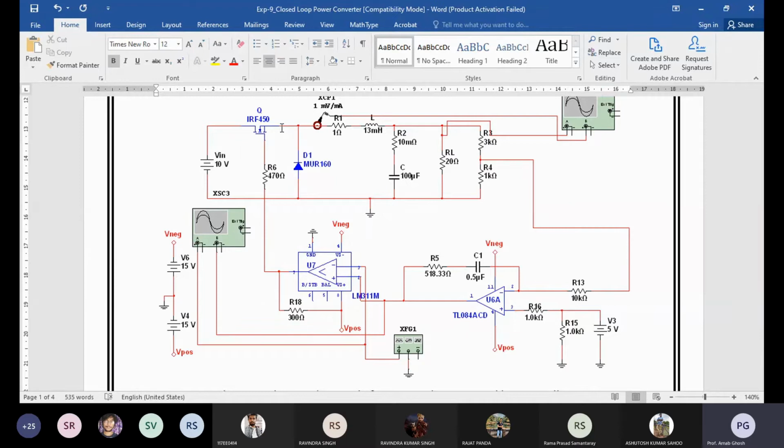If it is varying, your DC value also changes, but the repeating sequence is fixed, and the frequency of the repeating sequence decides the frequency of your switching device. Okay, so the varying of that control signal means the PWM also varies, and as per the variation of that value you will get the output. Okay, converter output, basically armature input voltage, also changes. Then again the motor will be regulated. So in that way you can regulate the entire system.